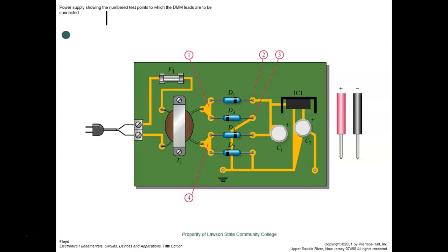So this is a printed circuit board, guys, and we'll look at this. You can see how these things are laid in there, and we'll show y'all how to check these things. A lot of times when we buy these, they're going to integrate them inside a package. So this guy right here is the same thing. It's four diodes in here. We'll show you how to check these. These are what you're going to run into most often. Instead of having these 4 diodes, you're going to have one of these in there.